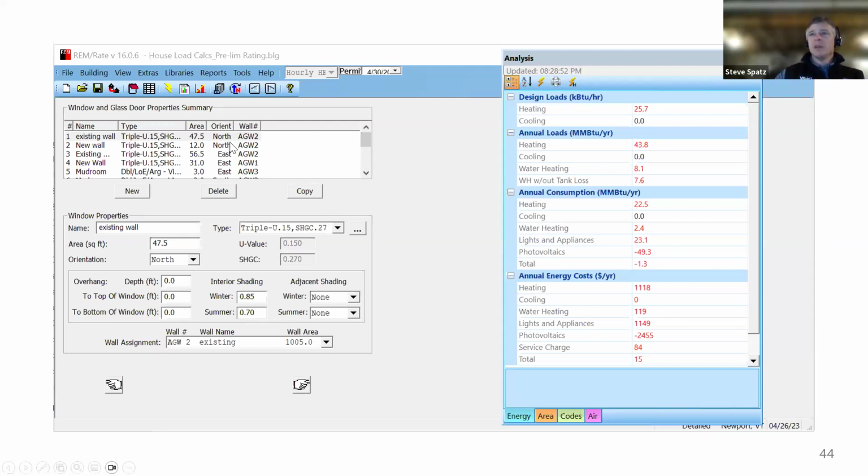So, this is taking into account very specific details of orientation, which wall type, if they've got different wall types or different assembly components, and this comes into play if you have an addition or existing components of the building as well as new. Taking into account orientation, any overhangs and shading. If you have deeper soffits that are partially shading the windows, you're actually accounting for that in the inputs here. So it really goes into, again, pretty granular detail in each of the components that you're entering.